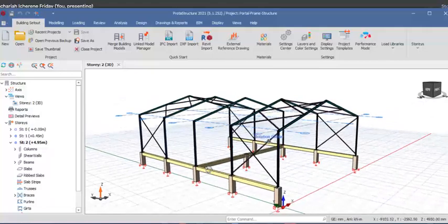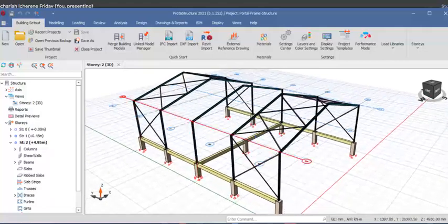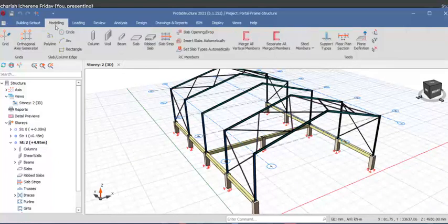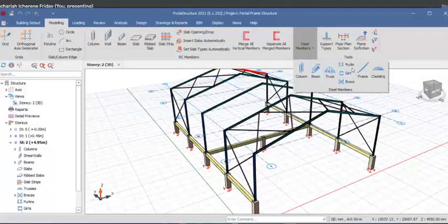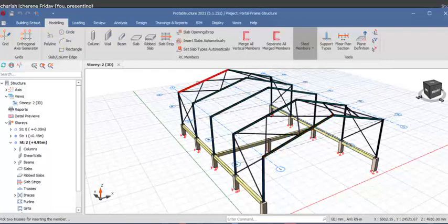Okay. So now what we do is the roof lines. We will be instructing the roof lines. So we will navigate to the story modeling tab right there, and then get to the steel members, and then you have polylines. Click on the polylines option. So once you click on that, you will have to select the rafter, first rafter, and the last rafter.